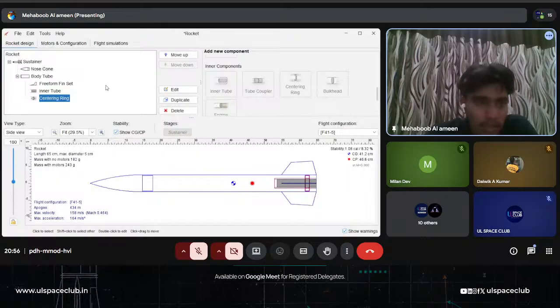So we don't need this much thickness. I'm just reducing the thickness to 1 itself. So which is fine. And also you can change the material. For centerings, I would try to change the material to some wood or something because it should be rigidly placed in there.